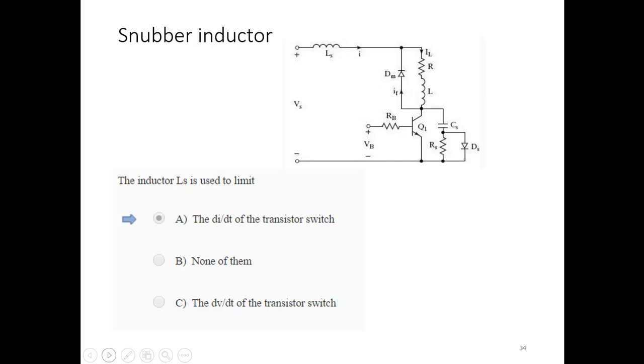It's very important. Like we talked about before, if a transistor is on and there was a freewheeling action from the previous cycle, the diode was conducting, right? The diode was conducting and current was flowing through this freewheeling diode because of the inductive load. Now in the next cycle you turn on the switch.